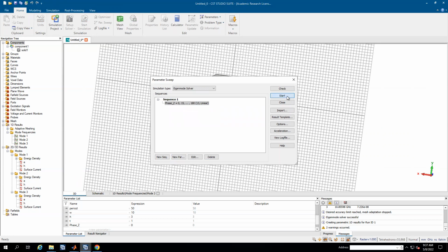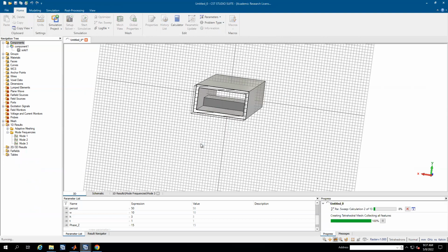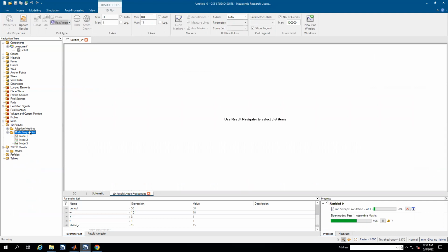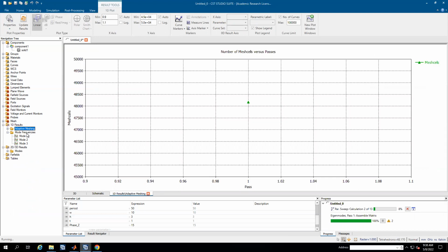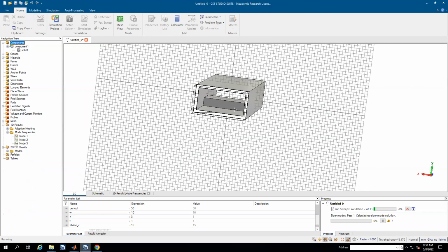And you need to store this. So actually this is equivalent to running multiple points for the Eigenmode solution. And if you go here, yeah, now we have this point just for phase equals 0. What we do, we're going to find the other points and it keeps going until we have a dispersion curve. So I'm just going to wait maybe for 1 or 2 points, just to show you the curve.